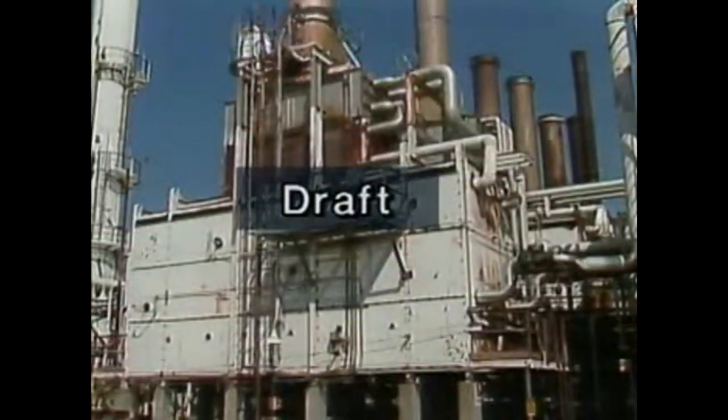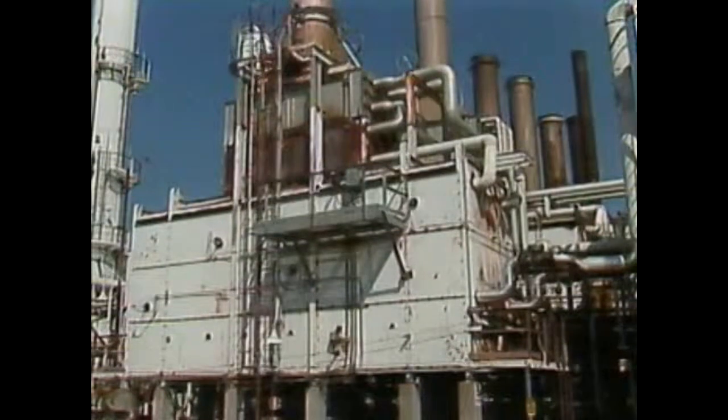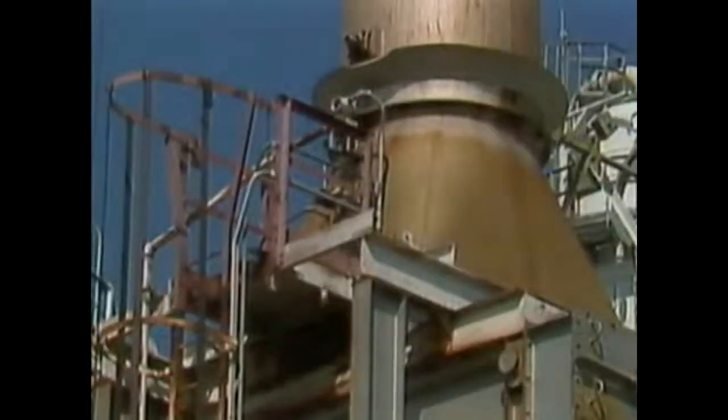Draft is often determined by measuring pressure at different spots in the furnace. In this case, there are pressure transmitters that measure draft at the top or arch of the radiant section and at the base of the radiant section, in the firebox, that is, in the area where combustion occurs. Draft may also be measured in the stack, typically at a point below the stack damper.